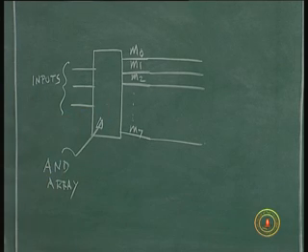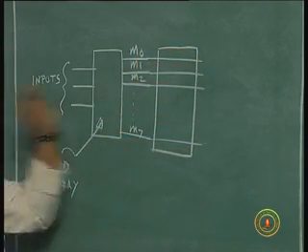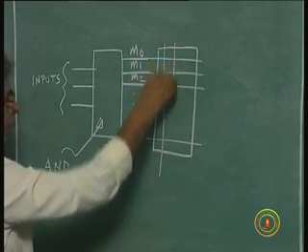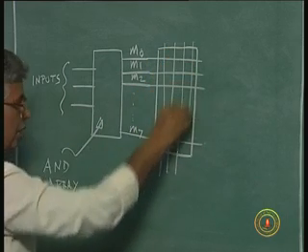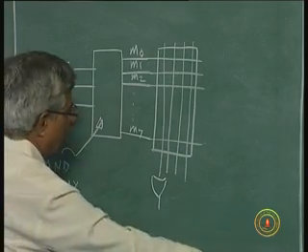So, how many OR gates must be there depending on the number of outputs required? There are 4 outputs required, W, X, Y, Z, 4 OR gates in which all the 8 inputs will be fed. I should be able to retain some of them, disconnect some of them. Do you understand what I am saying? So, I will draw this symbolically, even though it is very difficult to draw these 4 OR gates with 8 inputs each. Symbolically, I will say there are 4 outputs W, X, Y, Z, which is nothing but a combination of this. Maybe I should draw it a little bigger.